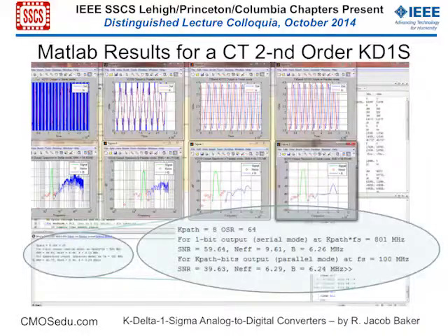So here's the MATLAB, some of the scripts, and 8 paths shows what the signal-to-noise ratios are. This is interesting. Serial mode means you recombine the data in a register, boom, boom, boom, boom. The parallel mode means you wait for the 8th path to get done, and then you shift the data out as a sum. So you're summing all 8 paths.